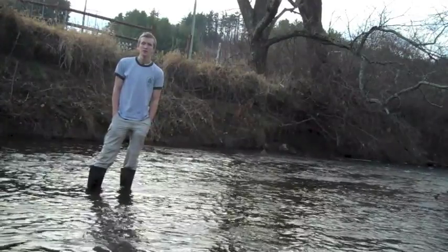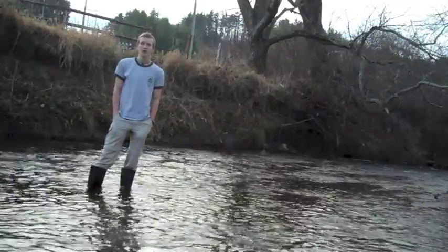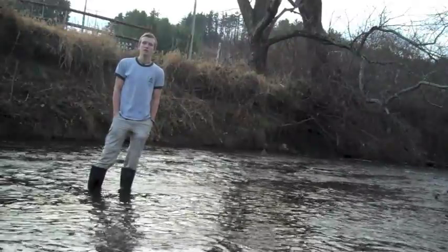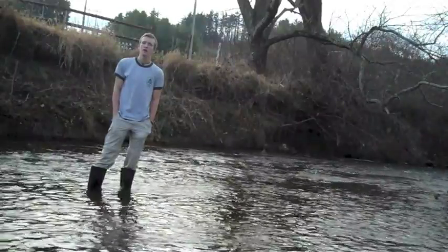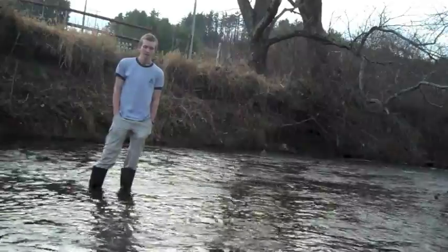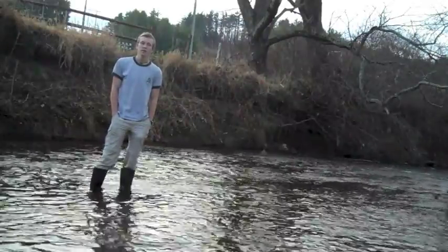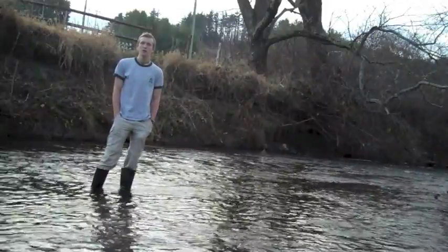In this demonstration, here in Boone, North Carolina, on the New River right by the State Farm parking lot, I will be showing you how to calculate the amount of flow of your river, creek, or stream to better assess whether or not your resource is a viable one for a microhydro power unit. There are three main methods of going about this: the Weir method, the 5-gallon bucket method, and the float method, which I will be demonstrating now.